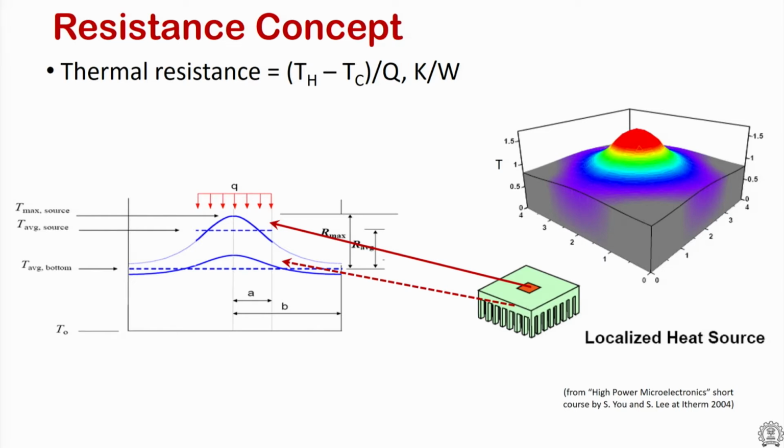So, these are the right way of defining these, and if one defines based on max temperature, then we are probably not conserving the energy or the heat transfer rate. So, it is best, even though the industry would prefer to know the maximum temperature, that is the temperature we do not want the device to exceed, to define based on these average temperatures and then figure out a way to predict the maximum temperatures.